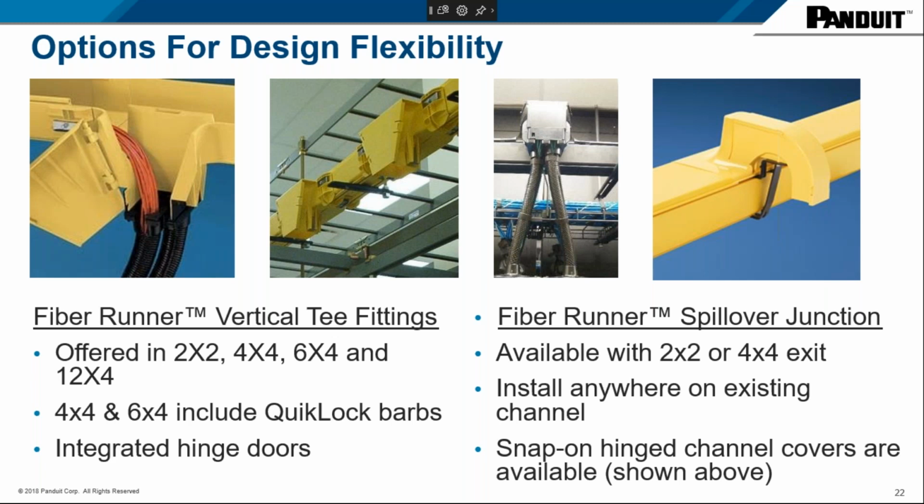So one thing I do want to highlight when we're working with such fittings, these do have to be planned ahead. As you're doing your design layouts and you realize that you do have height restrictions, these vertical tees and a lot of the other fittings do have to be planned ahead and designed before completing the installation, so you could be set accordingly. But again, this vertical tee that we do offer provides that great image that it is flushed against the channel. It's that aesthetic finish where everything is flushed against the channel, and it takes care of any type of height restriction.